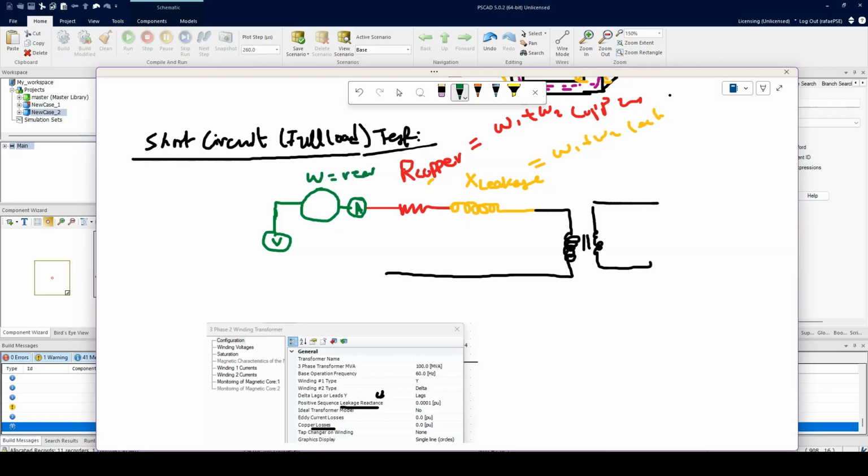It's only measuring real power, but in reality, inside of it, it has one coil which is in series with the circuit, measuring the current, and another coil which is in parallel, so it may have another line coming through and connecting. So you may see a setup like this, but don't get too confused about the setup. Really, the main thing is that this meter just needs one cable in series with the circuit, and the other cable might be coming out and connecting to the neutral. But all it's really doing is measuring real power.